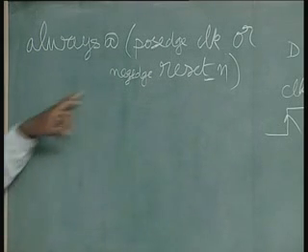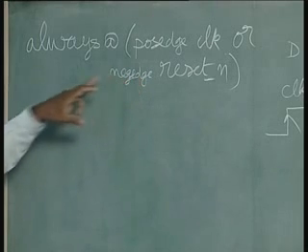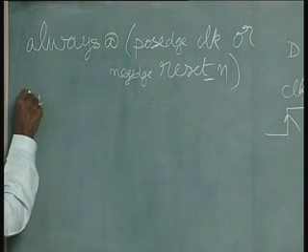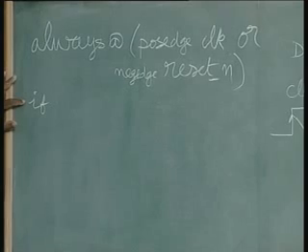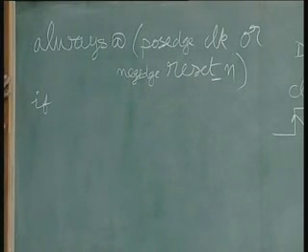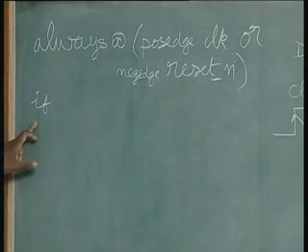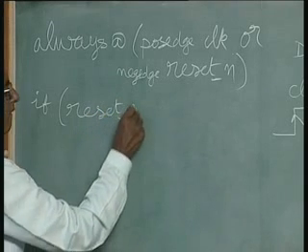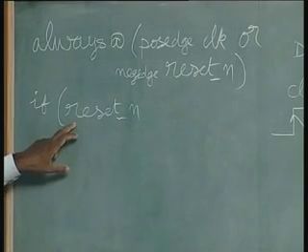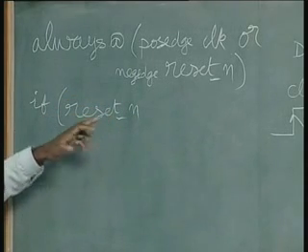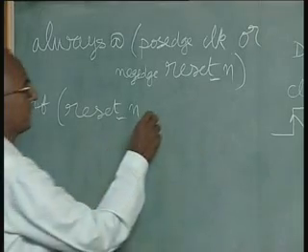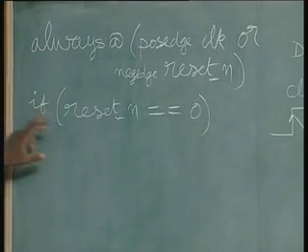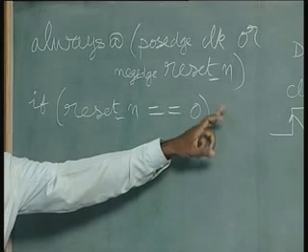And now coming to this, we have already accounted for negative edge of reset, but when we write for reset, how do we write? We use a new term called if statement. This is similar to C, the if-else you have used in C. If you use if here, what you can do is just take this reset underscore n, and we are going to see whether it is high or low. In this case, it is active low, so we have to check for 0 as such. Notice that after if there is no semicolon, this is a very important thing.